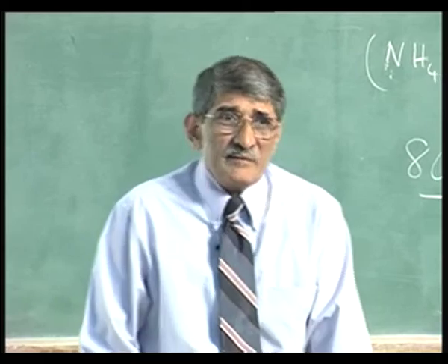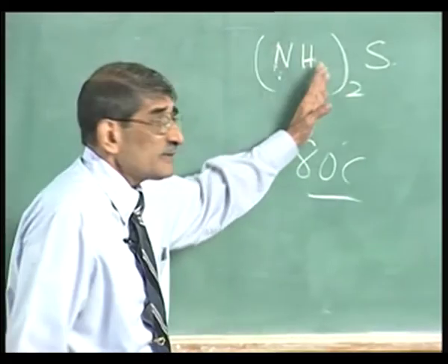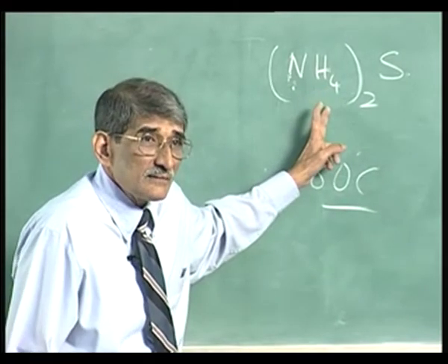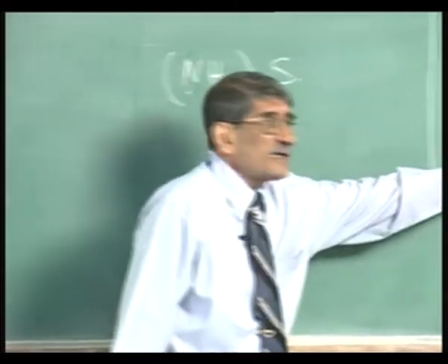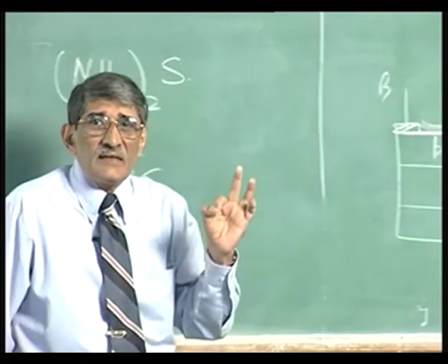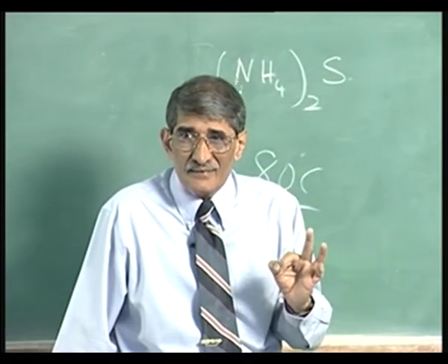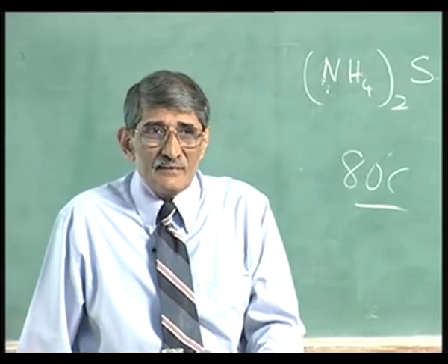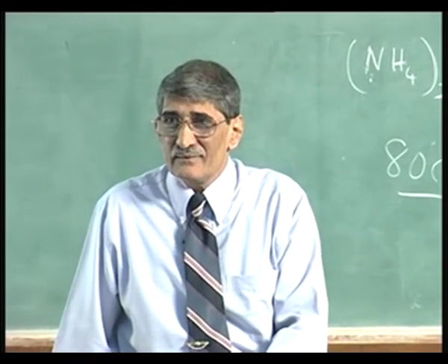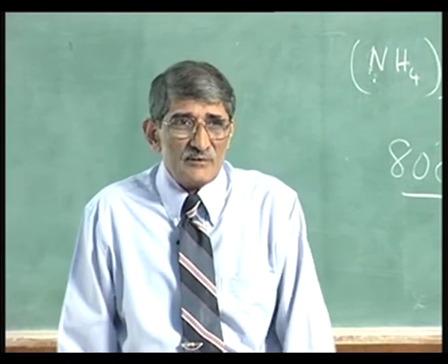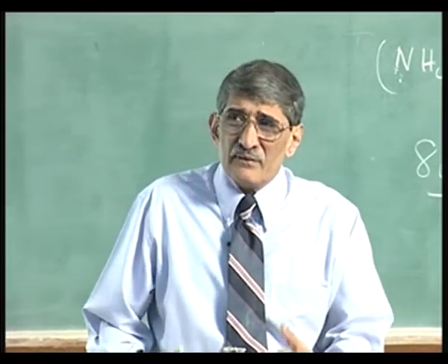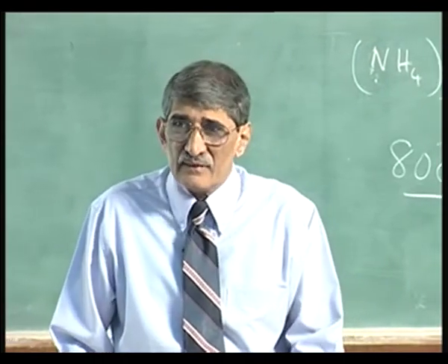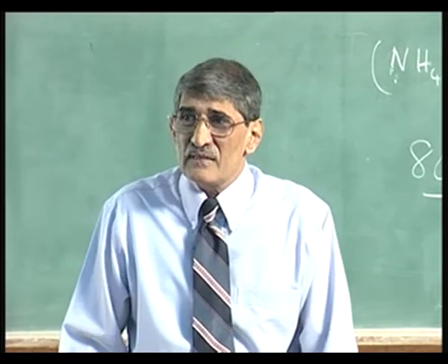The stability problem, which was found out a little later, is because when you put this particular layer, the surface should be very clean. There should not be any oxide layer. If there is any oxide layer, then that oxide layer will react with gallium arsenide to release arsenic. That is what was happening. The surface recombination velocity was not as low as you want it to be. There is still a lot of recombination taking place, till they observed instabilities.